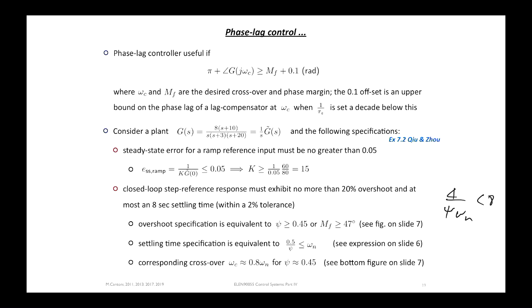And we can think of performance in terms of the desired transient behaviour of the closed loop, and that's more to do with what's happening to the open loop transfer function around the frequency where the magnitude will be 1, the so-called crossover frequency, and the phase margin.